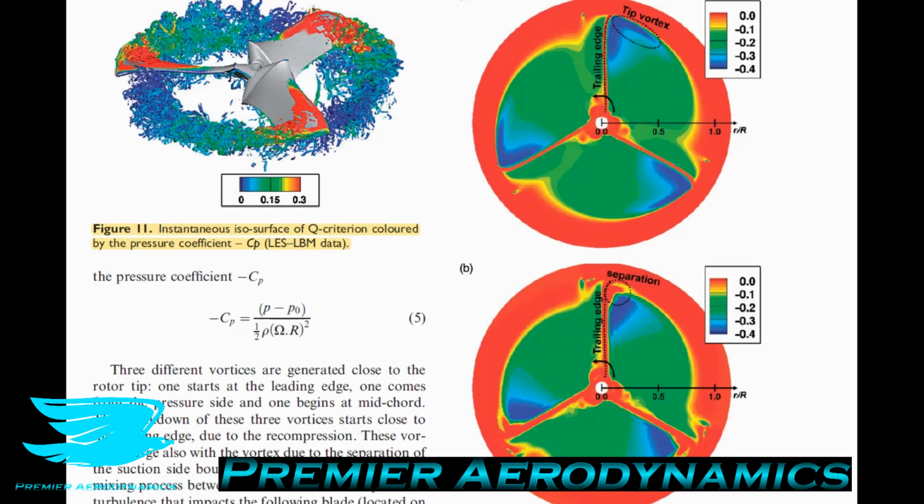In the case of the LBM, a boundary layer separation is observed on the suction side of the blade, and the tip vortex has a low influence on the flow at this location. On the URANS flow field, though, the influence of the tip vortex is well highlighted, and its influence on the velocity field is observed even far downstream of the blade. So in other words, these vortices persist further downstream. And this is probably due to potentially the turbulence modeling, the model that they had adopted compared to the LBM method. That could well account for the differences in the vortex breakdowns.